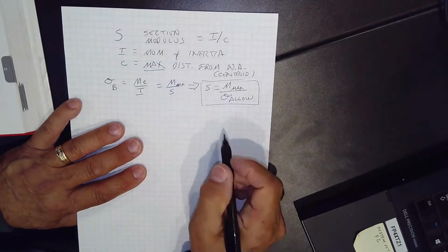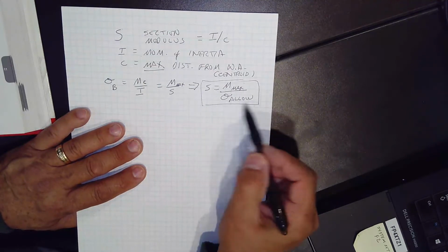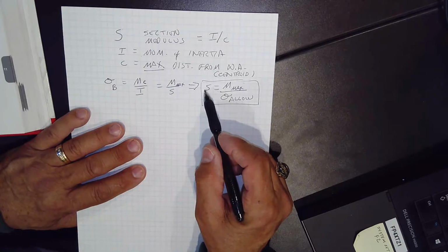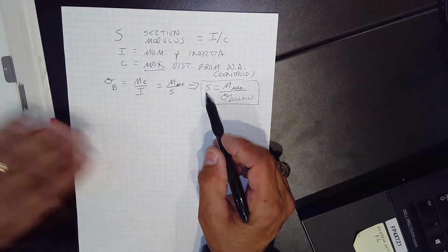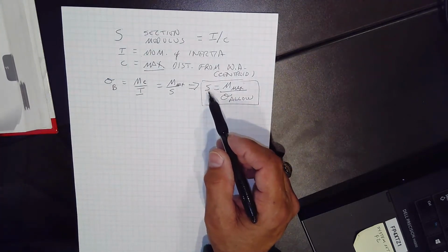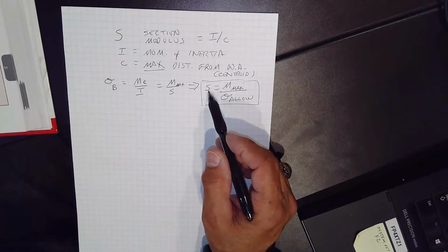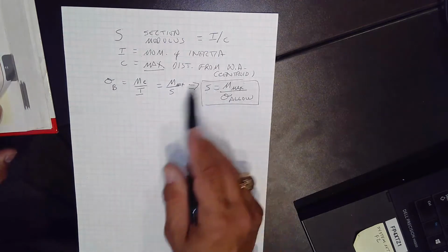And so what that's going to allow us to do is, given a moment and given an allowable stress, define the cross-section of the beam. And we're just going to look up the answer, because we're dealing, as I said, with existing shapes. Now, sometimes you may actually have to design the beam, but what we're going to focus on is ones that we just look up.